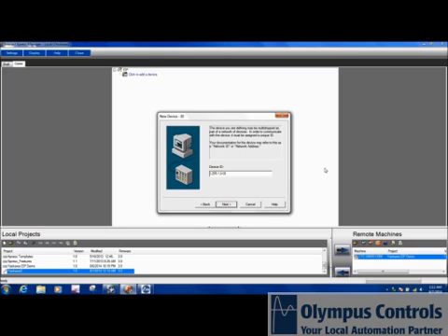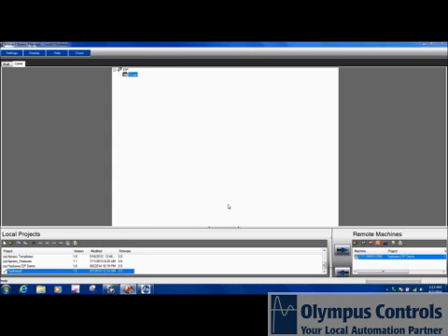What it consists of is the Ethernet IP address, which is 192.168.100.10. Then a comma. The next bit of information is the path, which is the backplane. And for Allen Bradley, the next number is a 1. And then since our CPU is in slot 0, with the CompactLogix there are no slots for the CPU to plug into, so the CPU is in slot 0. So IP address, comma 1, comma 0 for this CompactLogix. Hit Next and just accept the defaults. And then click Finish. So now we have a CompactLogix set up on an Ethernet IP network.